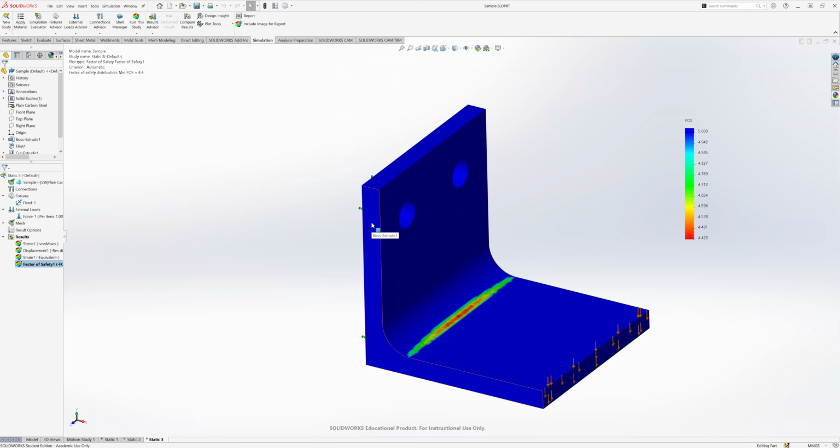This is what I was talking about before, where you're going between CAD and CAE, between modeling in SolidWorks and your simulations, to keep modeling, analyzing and refining your model to get a good factor of safety for your application. You don't want an extremely high factor of safety in any areas, and you obviously don't want a low factor of safety either. If that makes sense.